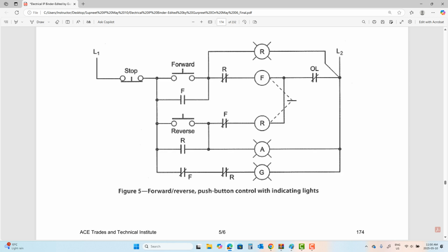So it's a power indicator. It's like a laptop's power indicator. Because if I push either forward or reverse, either the F contact will open or the R contact will open, and the green light will shut off and amber or red will turn on, depending on whether I'm doing the forward process or the reverse process. So what's the essence of a green light? It's nothing but a power indicator saying that the circuit is live. Cool? Keep going.